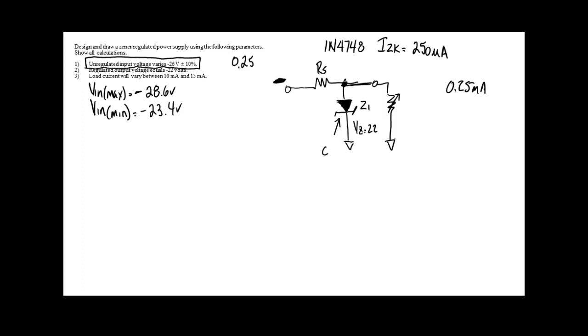To make it operate like a Zener, if I put the cathode up, it'd drop about 0.7 of a volt. So as long as you don't exceed the breakover voltage of a Zener diode, it acts like a diode. So when I check one with my ohm meter, it checks like a diode. I can't tell if it's a Zener or a diode, because your meter is not going to break the diode open.